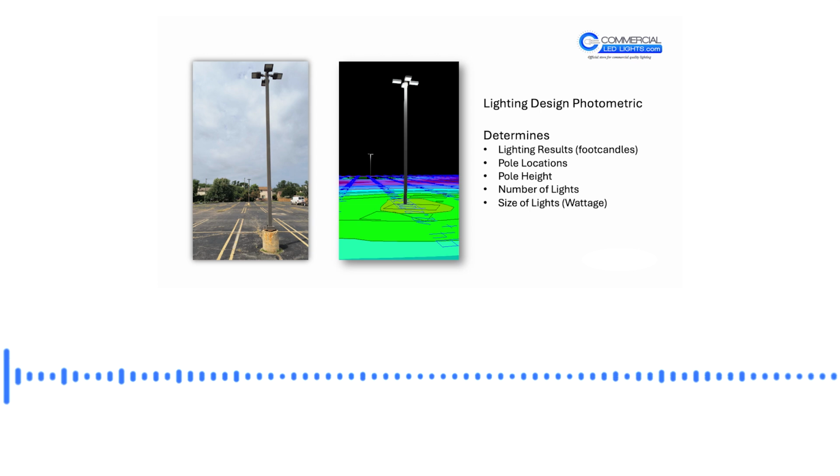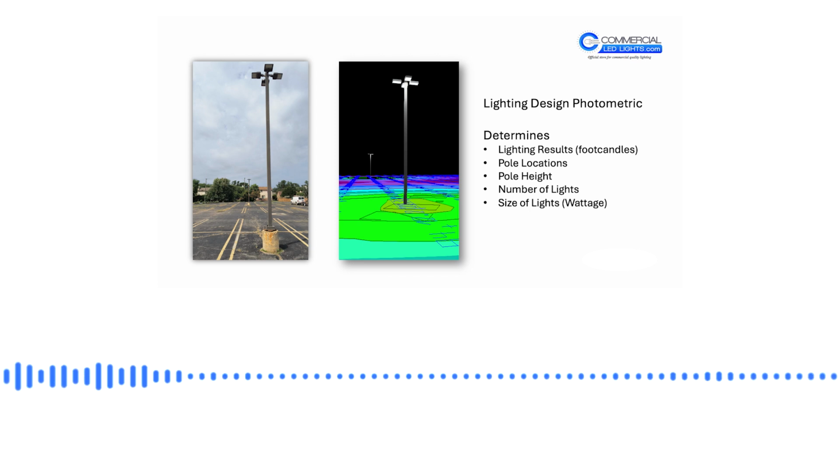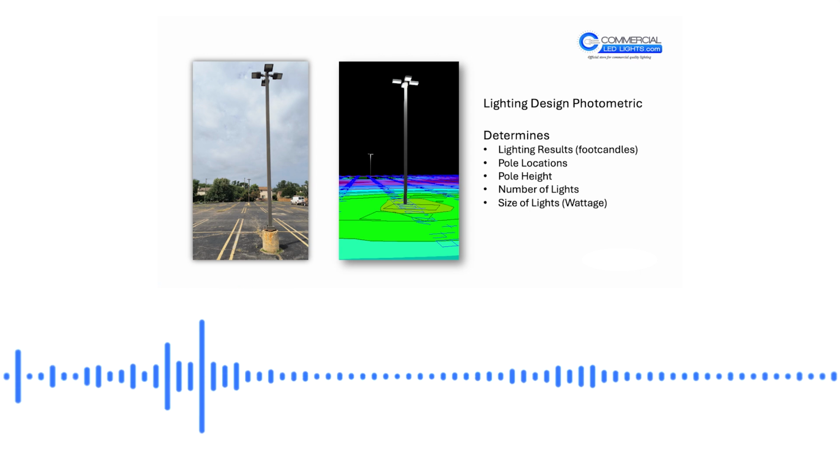Additionally, on top of poles, usually mounted to the top or the sides, there's often other tenons or other attachments that might need to go on the light as well. A bullhorn, for example, if you're mounting 2, 3, or even 4 lights on a pole. So that is the next step in terms of determining what pole you need. As you can see, there's a lot that goes into it.